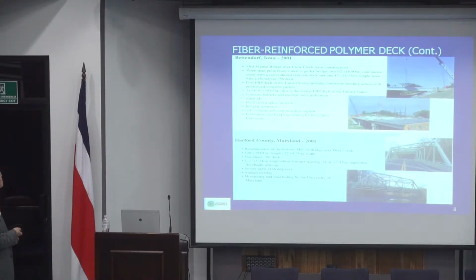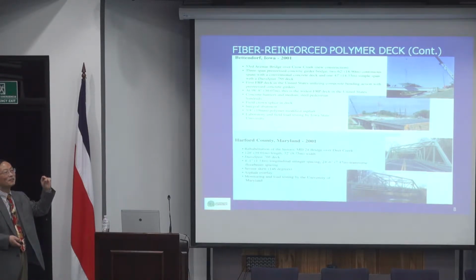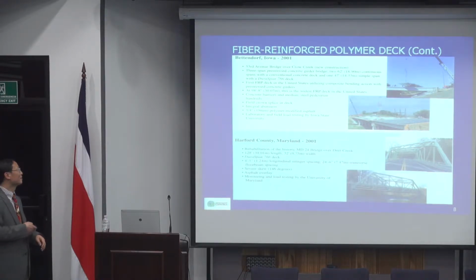After that, you typically do a pavement on top. This pavement is typically very thin. They use an epoxy modified asphalt, not just regular asphalt, so that it does not need to be very thick.